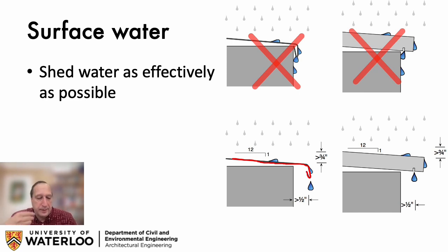It's like hemming a pair of pants. And that hemmed edge is to stiffen the edge to make it safer, not so sharp, but also stronger. But it also provides a spot for water to drip off. And that dimension is, we want it to be more than half an inch, and more likely something like 25 millimeters would be good.